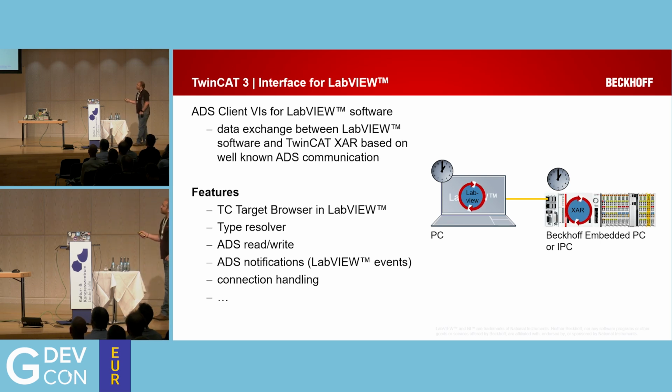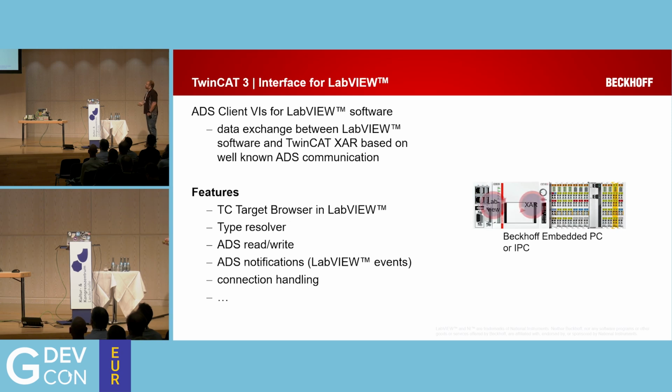What we ended up doing in reality was not running LabVIEW on a separate computer. We actually ended up running it on the Beckhoff IPC. We realized we had more than enough overhead for them to deploy their LabVIEW application as an executable onto the Windows system running on our Beckhoff IPC. Okay? Which made life a lot easier for us. It meant less cost. We didn't have to worry about too much about networks. And they could then control that using their own internal processes.